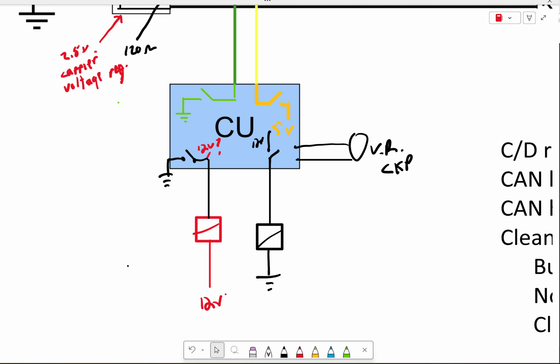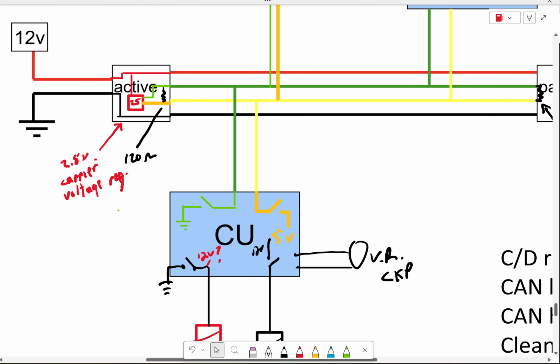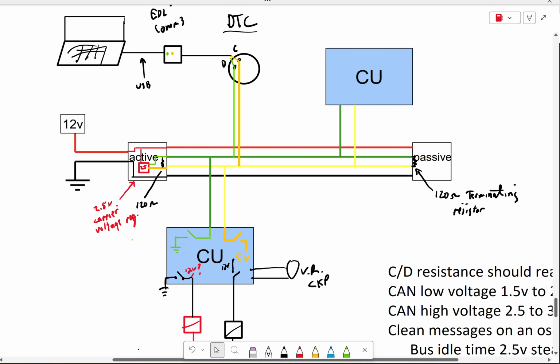We have these discrete outputs. Okay, that means the controller directly controls that coil of wire, that solenoid. Okay, so if that crank speed sensor signal would be useful to more than, say, just the engine controller. Maybe the instrument cluster would like to know that too. Maybe the transmission controller would like to know that. I mean, historically, what we could have done was had multiple crank speed sensors, each sending their own discrete data to each one of those relevant controllers. We don't do that anymore. Now what we do is we take that crank speed data, we generate a CAN bus message, and we just broadcast it on the CAN bus to any relevant controller that needs that information. Okay? That's one of the benefits of networking things together.